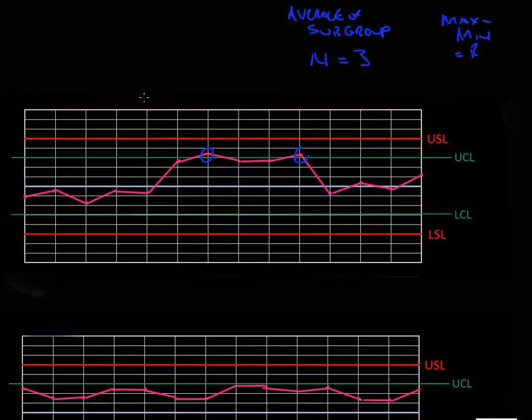But what you'll start noticing as you look at a lot of these control charts is you'll start noticing patterns. Okay, so let's take a look at this. First of all, we have some random variation: 1 up, 1 down, 1 up, down, and it's near, maybe slightly below, but it's near the nominal or the center line. And then something happens here, it jumps. Now take a look at this. Again, we already know a couple of those points go out, but within that range, it's actually fairly narrow. And then we see it jumps back down again to another narrow process range. So the trend we're looking at right here is jumps in data.